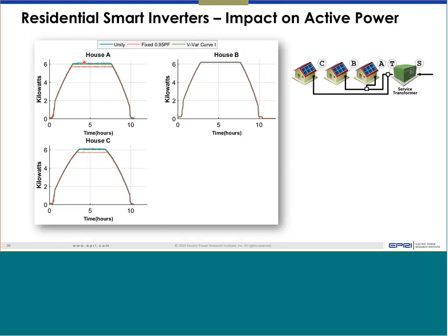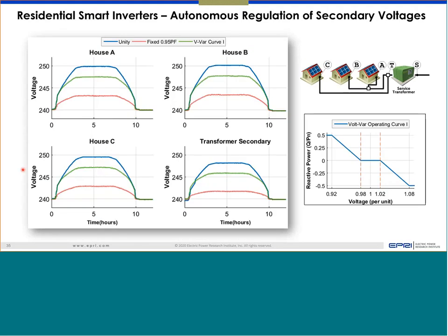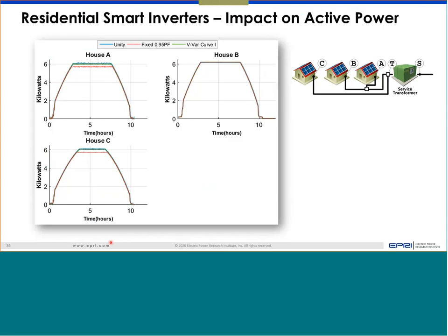This is an impact of high DC to AC ratio. If you know what I'm talking about, most plant designers now put a lot of solar panels behind a smaller size inverter. And we'll discuss why they do it. But the result is that for a longer duration power will be flat, and for a longer duration voltage will also be high and flat. So voltage will be flat at a high value for a longer period on a sunny day. That will be the outcome of the installer putting a larger size panel array behind a smaller size inverter. So the power is the same, even if it's, say, a 6 kilowatt inverter, they may have put 7 kilowatt DC.